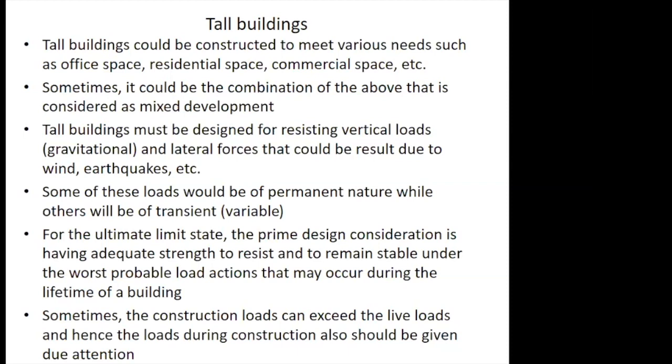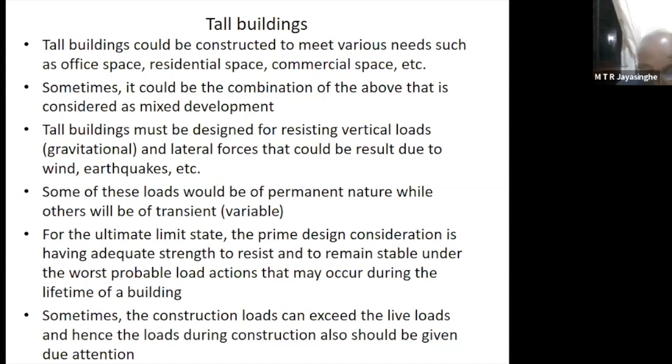So when it comes to optimum structures, again, we have to think of normal reinforced concrete structures, where say 50 to 60% of concrete is not doing anything. For example, in a slab, we have hogging moments and sagging moments in every section. Whatever the moment, below the neutral axis, the slab is cracked.